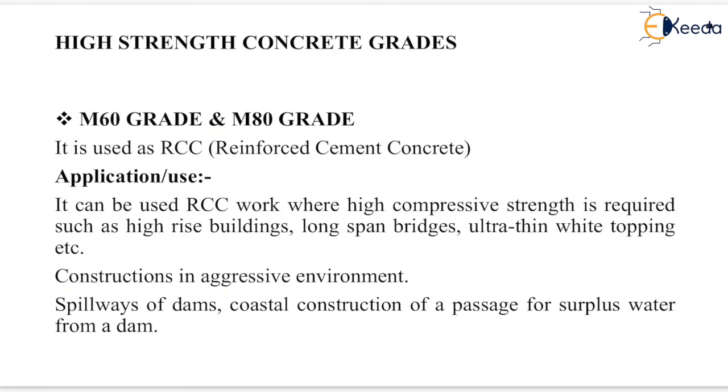Now the next concrete is the high strength concrete grades, that is M60 grade concrete and M80 grade concrete. It is also known as RCC, that is reinforced cement concrete. It can be used in RCC work where high compressive strength is required, such as high-rise buildings, long span bridges, ultra thin white topping, etc. Construction in aggressive environment, spillways of dams, and coastal construction, that is a passage for surplus water from a dam.